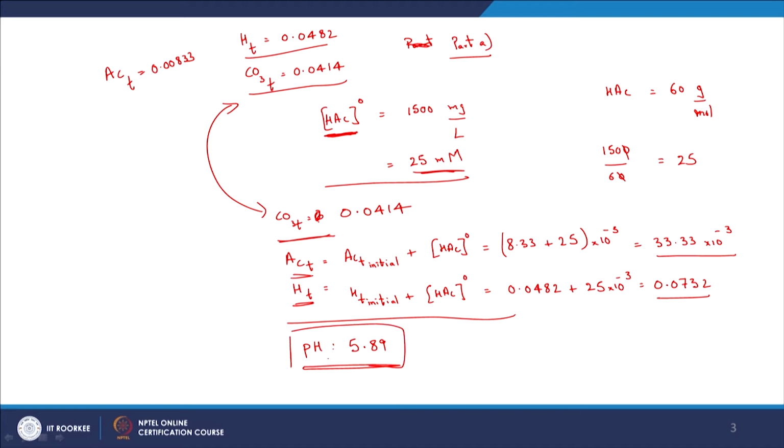Now once the digester went sour, as in the rate at which acetic acid was being produced was greater than the rate at which the acetic acid was being reduced to methane, right. So, what is happening here? You have accumulation of acetic acid. Thus you end up decreasing the pH, and we wanted to calculate the pH. Now it is 5.89, which is considerably less than pH 6.5, which is in general the lower threshold for effective production of methane, or for methanogenesis, right. So, that is this particular case. Now you see that the pH is less than what you want.